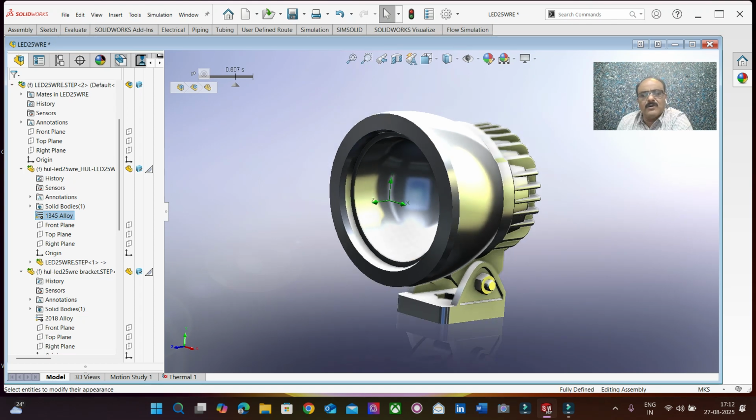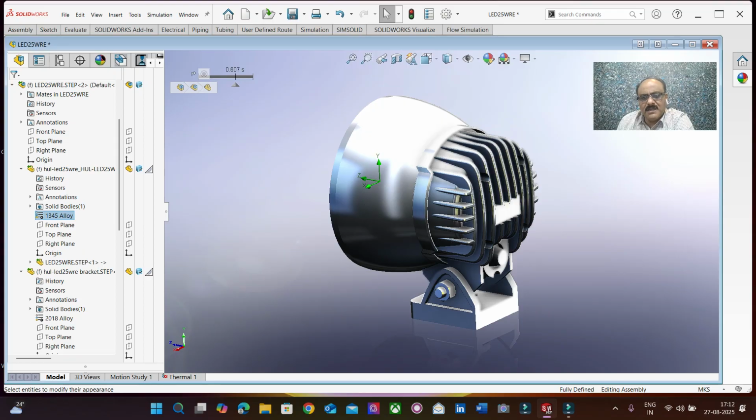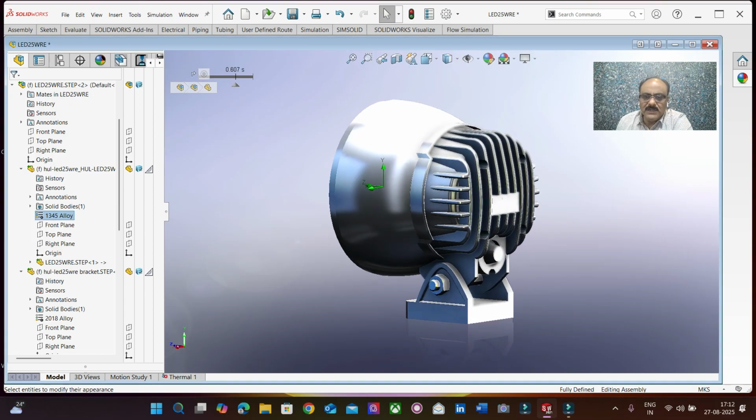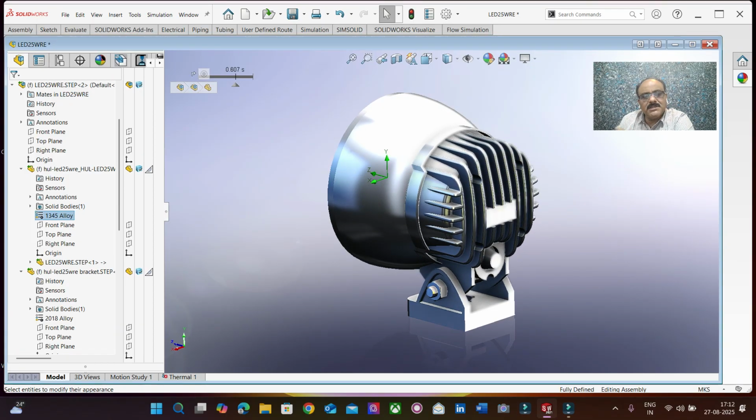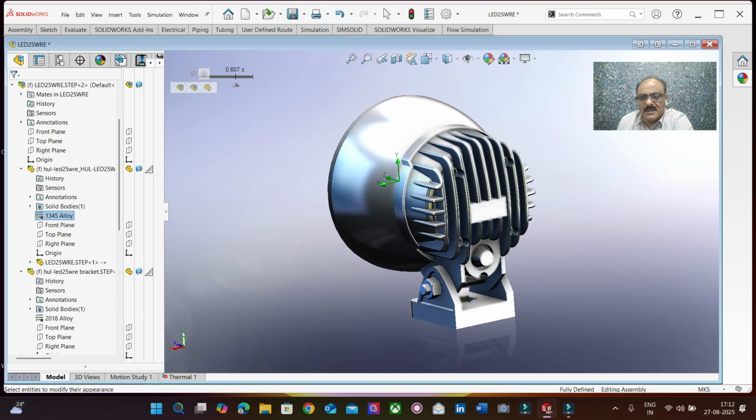Okay, I don't want to make it more cumbersome using a stainless steel surface, because cost is again a very important parameter. So cost is a parameter, the weight, bulkiness, but the bulk density is also going to be a parameter. And apart from that, the casting process, the machining processes involved in the manufacturing point of view. Okay, so we look out for a material that is more workable, and more ergonomical in nature.